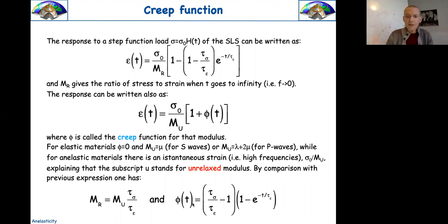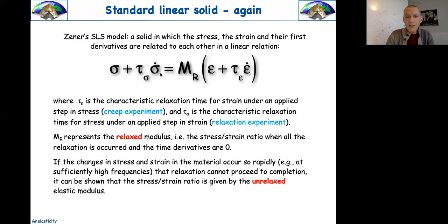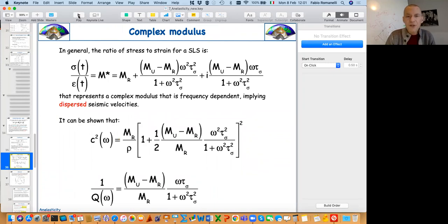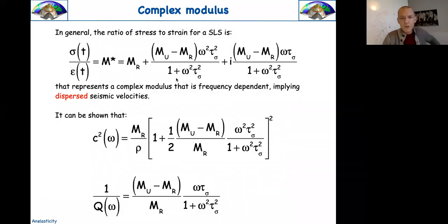So we generalized, for now, the standard Hookean rheology. We took a little bit of Newton, a Newtonian one, we added it, we built a standard linear solid, and now we have time inside. And we generalized the constitutive relation between stress and strain, including the time derivatives. Up to now, nothing is about seismology here. No, let me add one other, the most terrible one, then we will make a 1-minute pause.